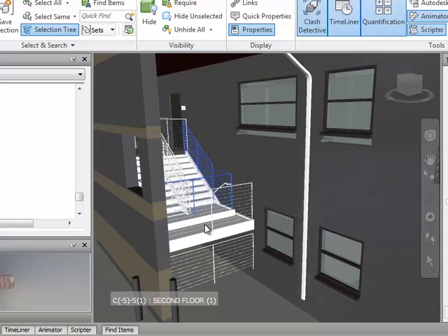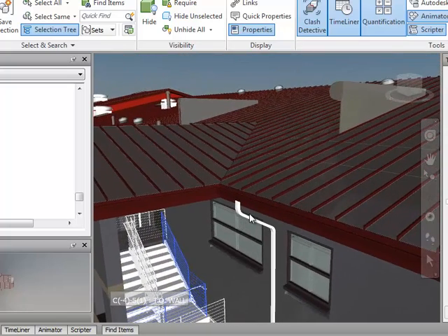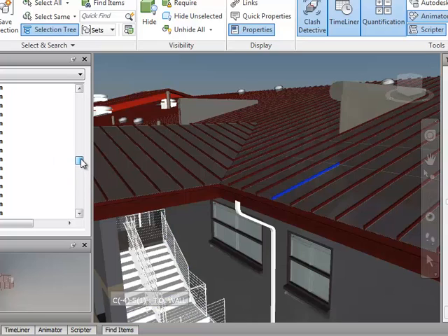I have another question. Okay? The roofing, not the ceiling, there are two parts of the roofing. One part is the substantial roofing, the one with the sticks. It calls them mullions. So for the purposes of taking off the roof, you only need the square footage of these panels. You wouldn't need to know the lineal feet of these mullions.